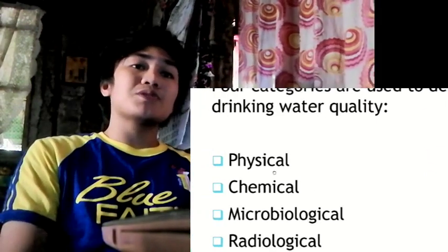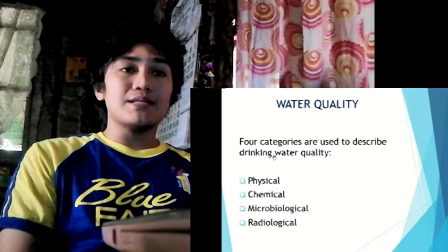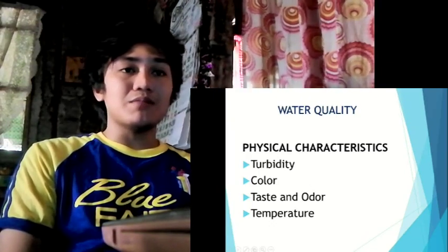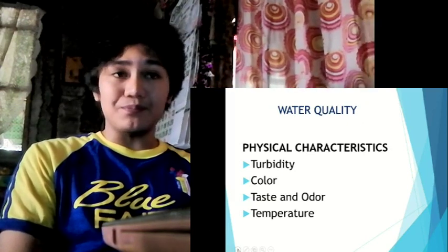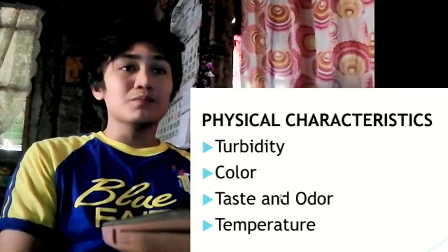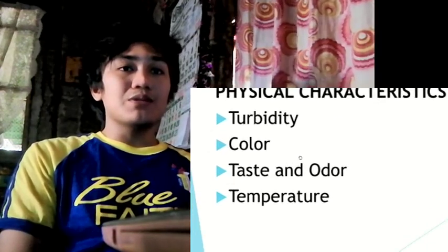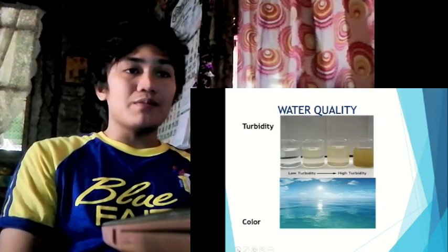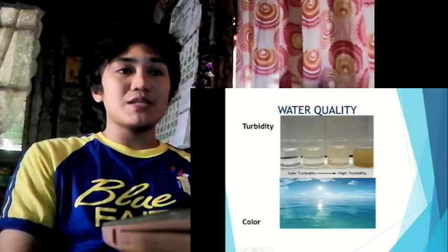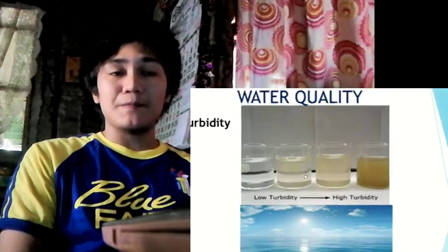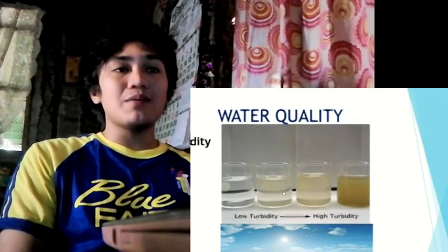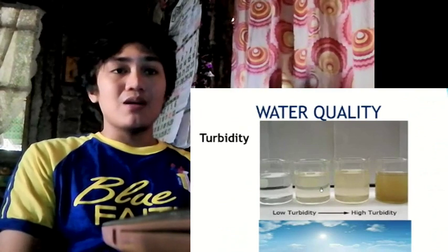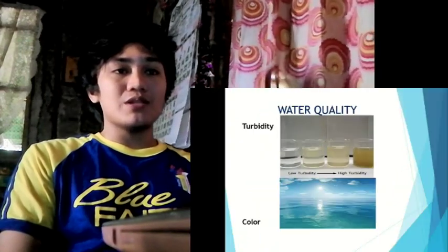Turbidity. The presence of suspended materials such as clay, silt, finely divided organic material, plankton, and other particulate material in water is known as turbidity. The unit of measure is the turbidity unit or nephelometric turbidity unit. It is determined by reference to a chemical mixture that produces a reproducible refraction of light. Turbidities in excess of 5 turbidity units are easily detectable in a glass of water and are usually objectionable for aesthetic reasons.